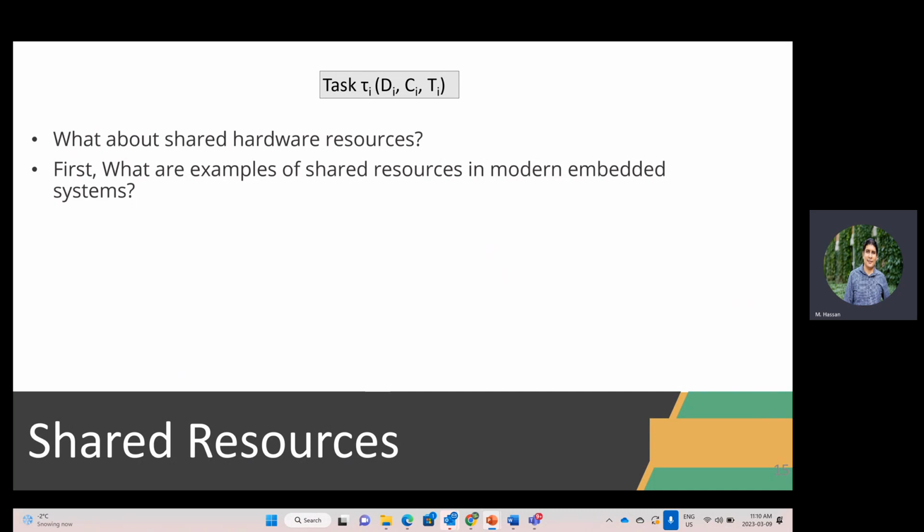What are some of the examples of shared resources? I already told you about critical sections or software resources. What else? What do you think, for example, might be shared resources in a Tesla SOC? Well, we have already given the examples of IOs before, right? When we talked about shared resources and scheduling, so accessing certain sensor, for example, the wheel sensor that goes into different tasks in a car, it's a shared resource.